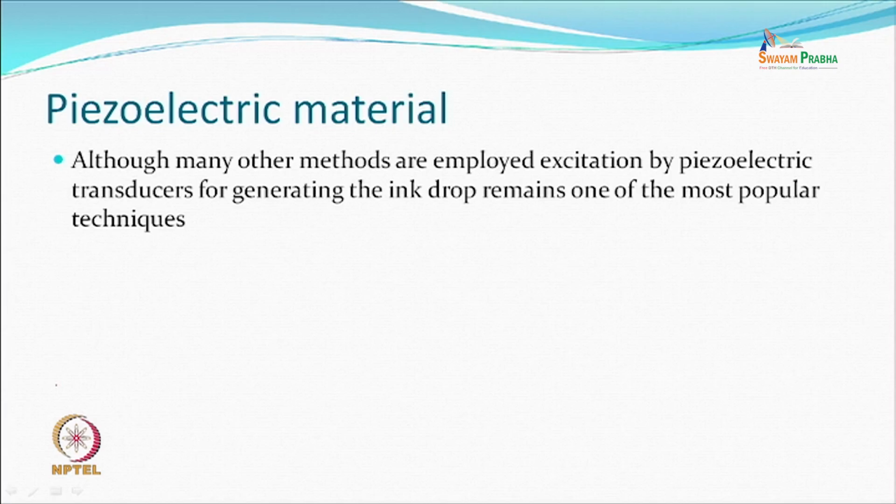One of the materials that is used to excite the ink surfaces or the bulk so that the volume within the chamber is changed, let us say by squeezing. A large number of piezoelectric systems may be used for generating the drop on demand process. So, piezoelectric material is one of the transducers.